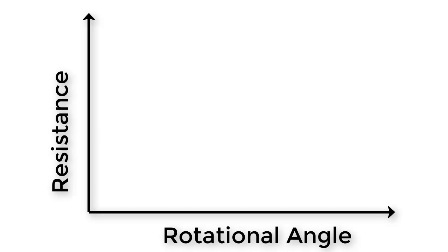Now, the sensor response curve defines the relationship between these two properties. To get the curve, I have to do an experiment with the sensor. I will start by placing the potentiometer dial at the 0-degree angle and reading the resistance out with, say, a good multimeter. This gives me 1 point on this curve. Then I will move the dial to a slightly higher angle and read the resistance out again. I will repeat this process until the dial is at its maximum position. Then I will reverse the process. Starting at the maximum position, I will decrease the angle little by little, reading out the resistance at each angle. Then I will repeat the experiment again and again.